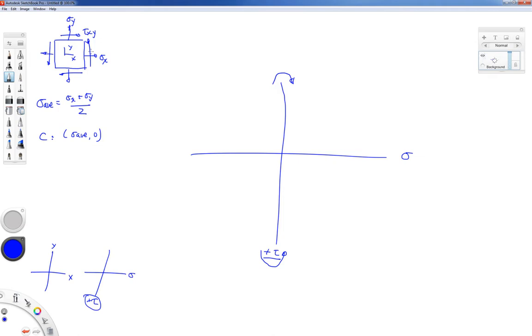If it rotates clockwise, that's counterclockwise, that's a positive shearing stress when it's on this face. Of course, if you look on the negative face or the perpendicular face, it rotates the opposite direction. Now, I find those little arrows kind of confusing, but a lot of books will do that.